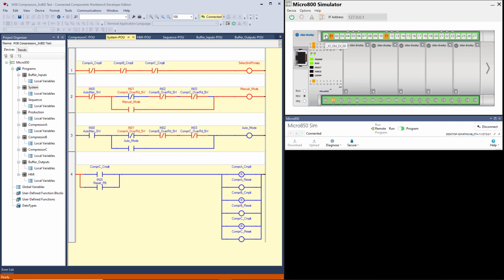Now I'm going to turn input 0 on, and notice that I lose my mode now. I don't have manual mode or auto mode, because if you try to change mode with an override switch on, you're going to lose it. So we'll turn that back off, and it automatically goes into auto mode, because we had this switch on.